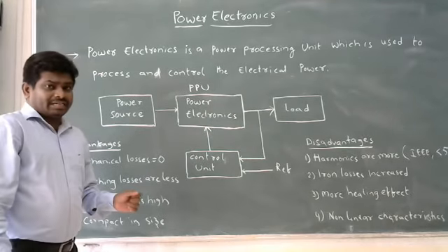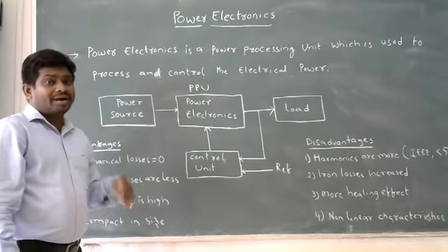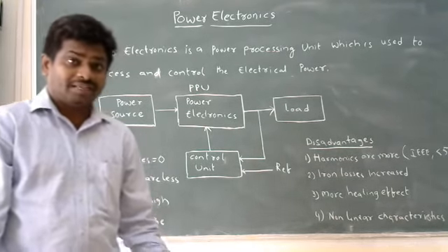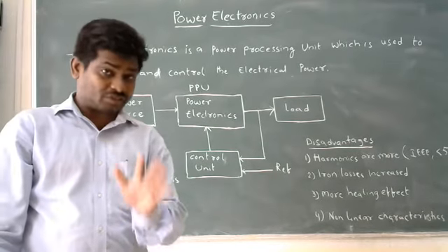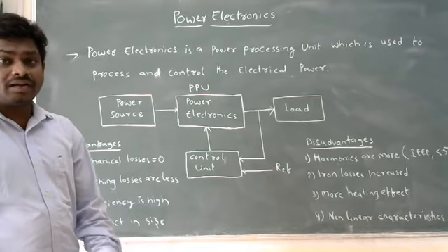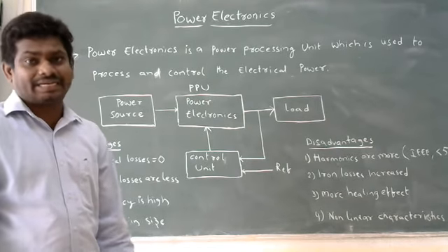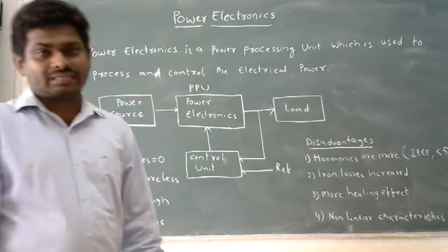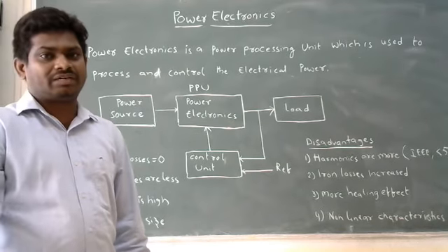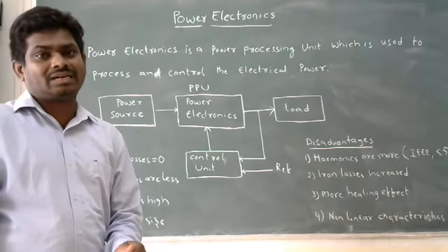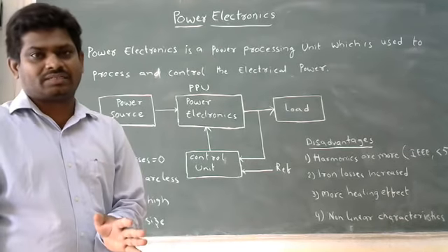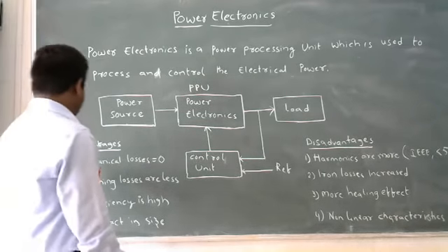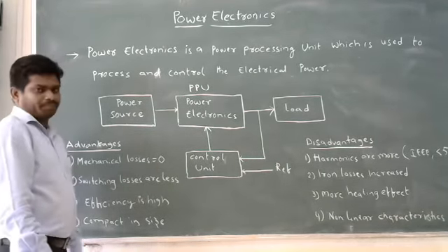When you take the DC generator, which is used to provide the DC supply to a synchronous generator to excite the field winding, that DC generator is a rotating machine. Then rotating losses, called mechanical losses, are present in the operation. But when you use power electronic circuits to convert AC supply into DC supply, there exist only very small switching losses, because of the absence of rotating parts in the configuration. Thereby, I can say mechanical losses are zero.